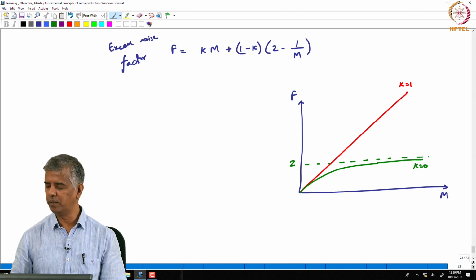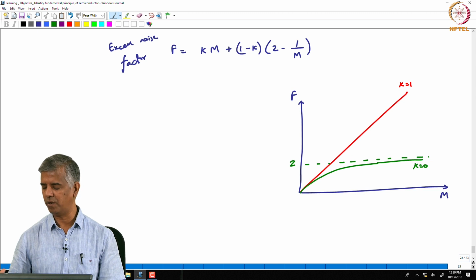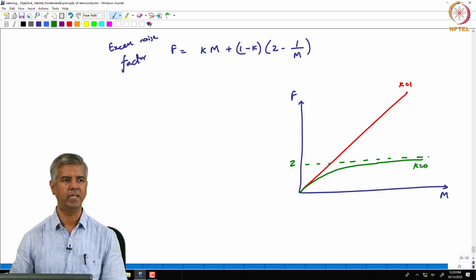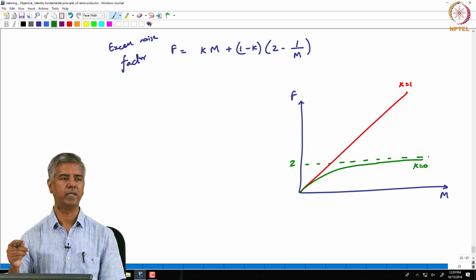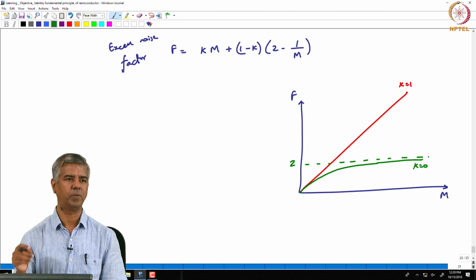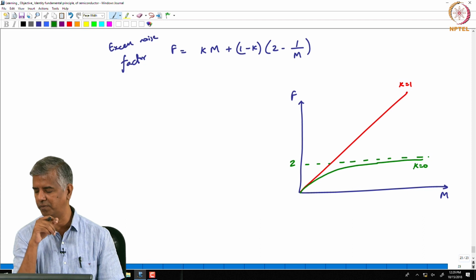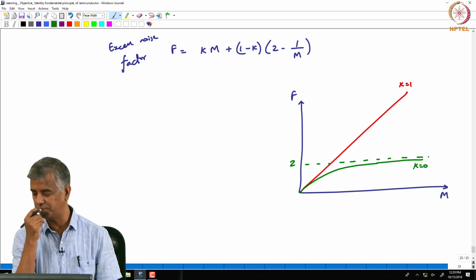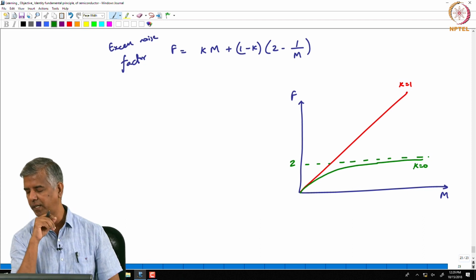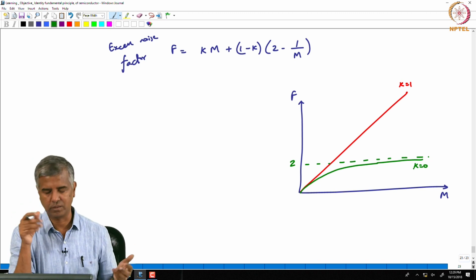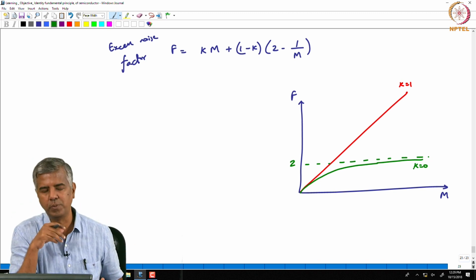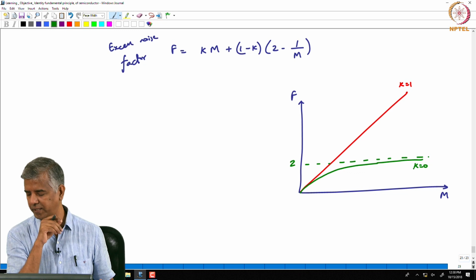So, beyond a certain value of m, all you have is gain and not so much of loss, because you do incur extra noise just because the electron is going to create that variability in terms of achieving gain. The gain is not a fixed value, but you do not get any more noise because of holes kicking in.